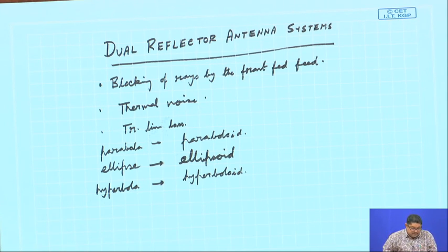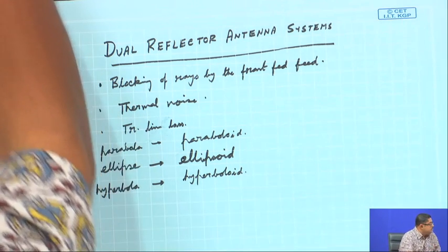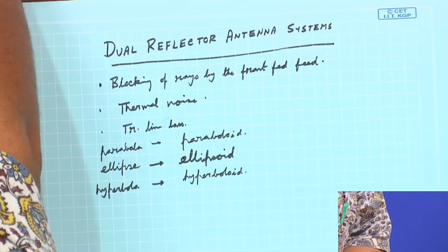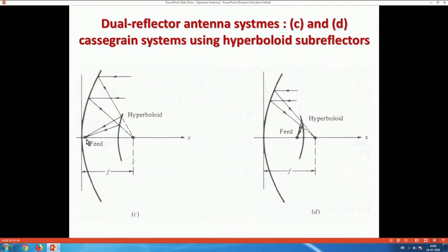In general, for Cassegrain reflectors, the feed is in a convenient position, as you can see that the feed is here. The feed is looking at the sky like the paraboloid, so it is not collecting noise from the ground.